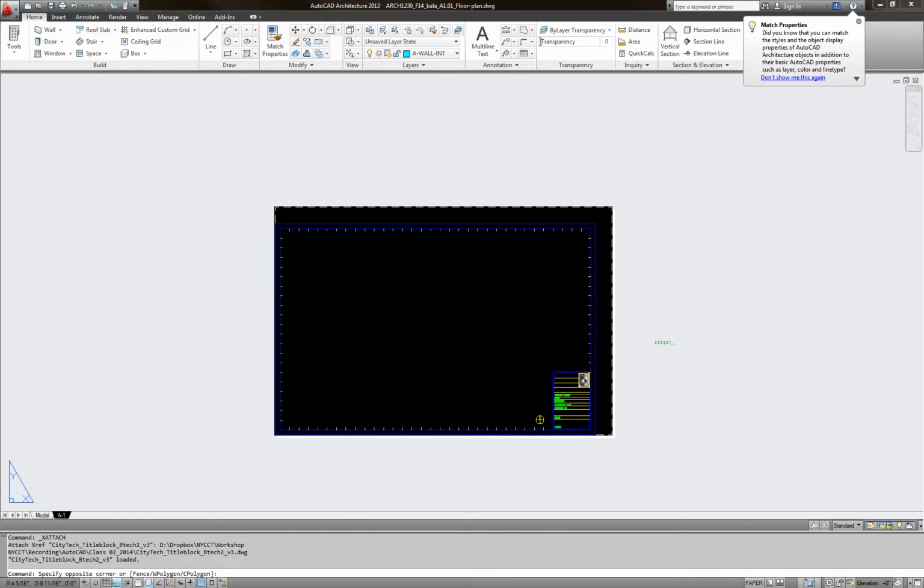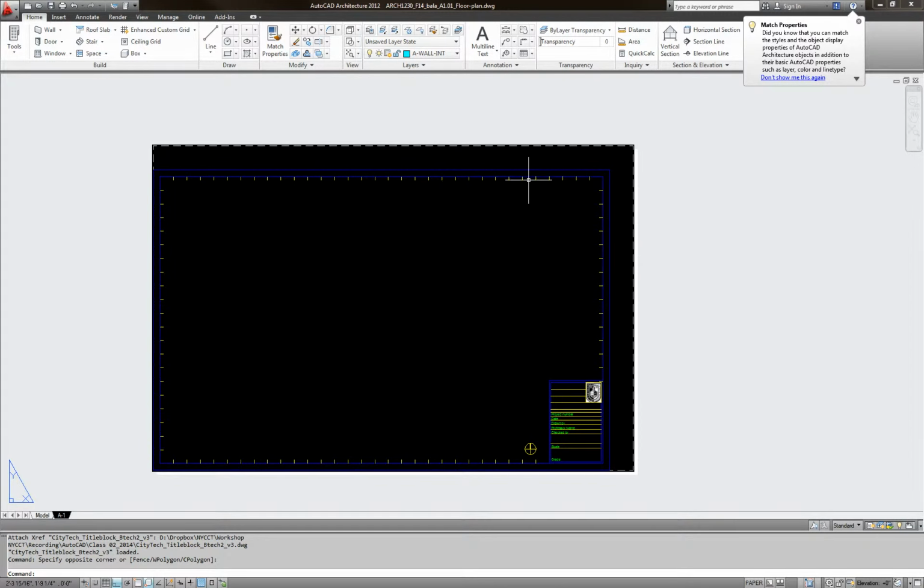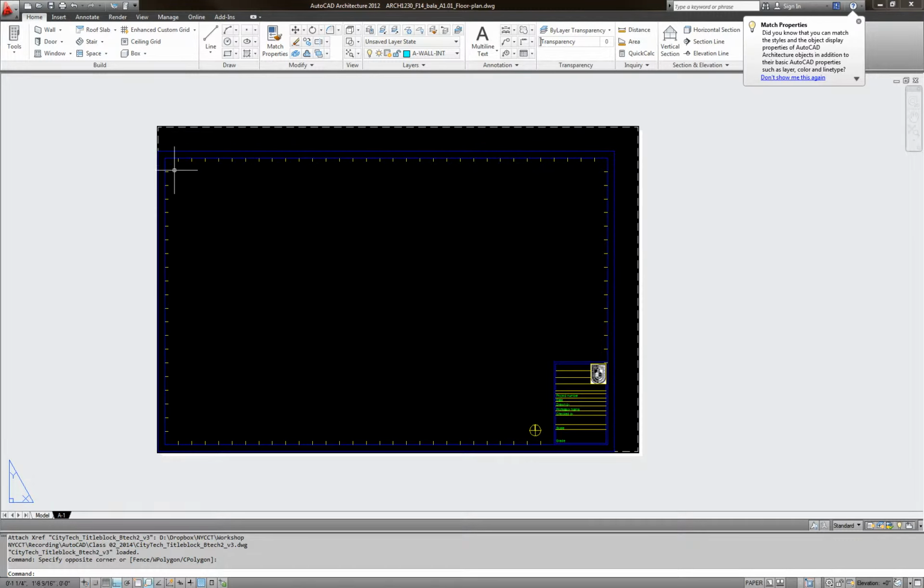Now if you look here, I have some of your title blocks set to 24 by 36 and this title block set to 22 by 34. The reason, guys, is that in our school we have 11 by 17. 11 by 17 is 11 times 2 is 22 and 17 times 2 is 34, so it's 1 to 2. So let me change this again. If your professor gives you 24 by 36, leave it the way it is.